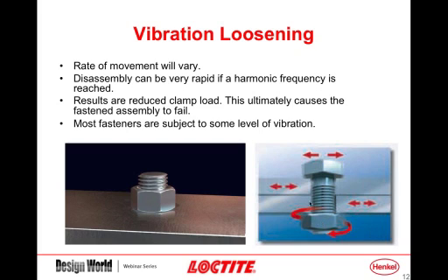This particular picture that we have right here, please keep this in mind. We're going to get onto a test rig a little bit later, and this is the basis of the test rig. It has two plates that are bolted together. It's called a Junker machine. A side sliding action is incurred between these plates, and it's a very effective test of different types of thread fastening devices to see how effective they are.